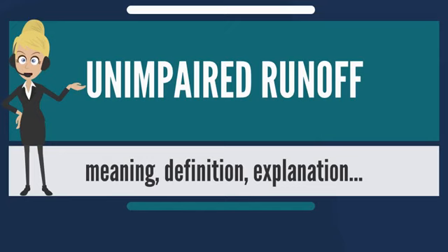The reason unimpaired runoff is important is because long-term hydrologic records are often used to develop relationships between precipitation, runoff, and water supply. By removing changes in the timing between precipitation and runoff due to human influences, the long-term relationships will be more useful. Calculating unimpaired runoff is also extremely important in identifying long-term climate change impacts.